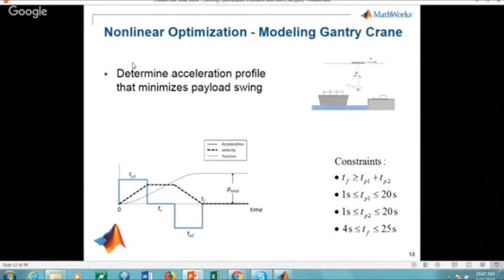It is mainly a nonlinear problem. You can define the input and output, x1 and x2, and what is the range of x1 and x2. Later on, you can create the function plot and visualize it. Then you can use solvers such as fmincon to pass the arguments: the objective function, the inputs, the inequalities, and then solve that. You'll get the final result, the minimum option.